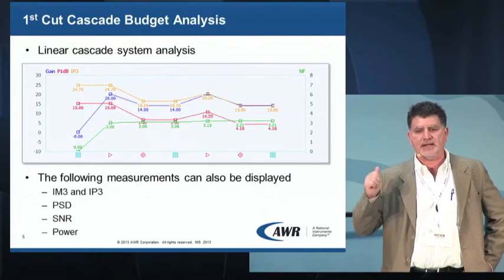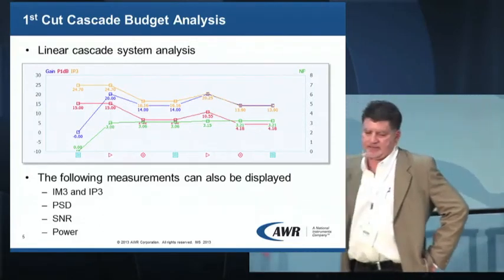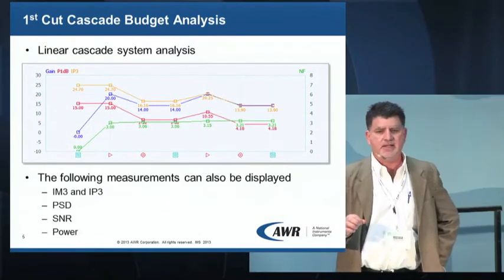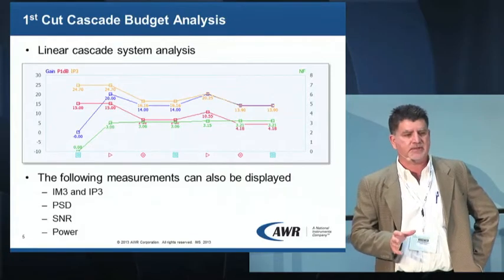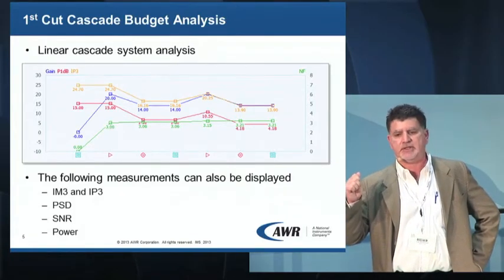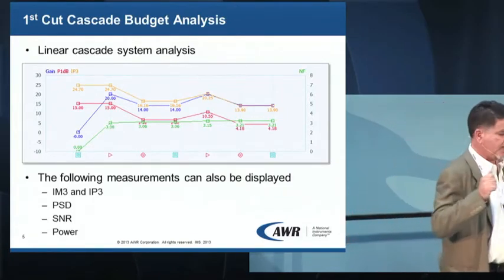Earlier I said you can drop the system, this RF architecture, into VSS, Visual System Simulator, and start accounting for mismatch between components and noise at image frequency. This is your first cut at budget analysis using the tool.